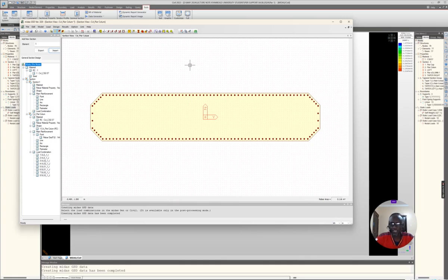If I had not specified reinforcement, I would be the one to come and specify the reinforcement using this area. Since you're adding these bars, I would do the points, or I would do the lines. If you do perimeter, it means you just calculate a circular one. I will just specify, and you look for a circular section. You do that. Now for here, you would do this reinforcement using the line. But I think here it has also given you the point, so it's like added. But I would also do the line.